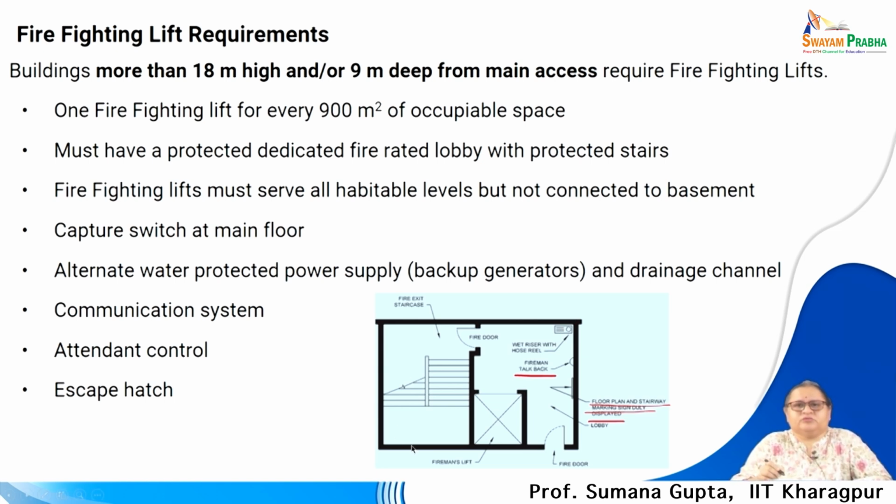Now, coming to buildings which need such a system: more than 18 meters height and or 9 meters deep from the main axis. That means, if the building from the road side is deeper than 9 meters, then you need a firefighting lift.